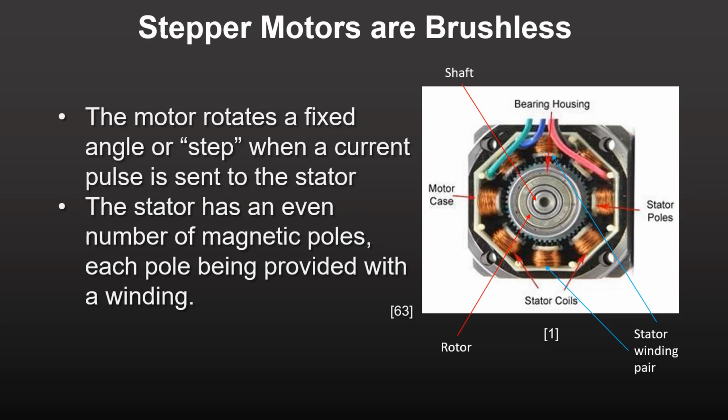Unlike other motors, a stepper motor rotates at a fixed angle and then stops. The fixed angle is called a step, hence the name stepper motor. Think of a stepper motor as a quasi-digital device as compared to all other motors, which rotate continuously and through all angular positions. Common stepper motors rotate at angles as high as 90 degrees and as low as 0.75 degrees.